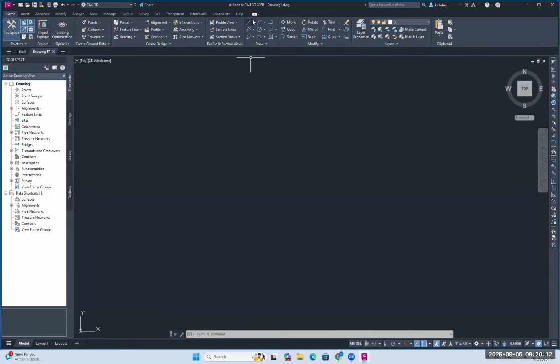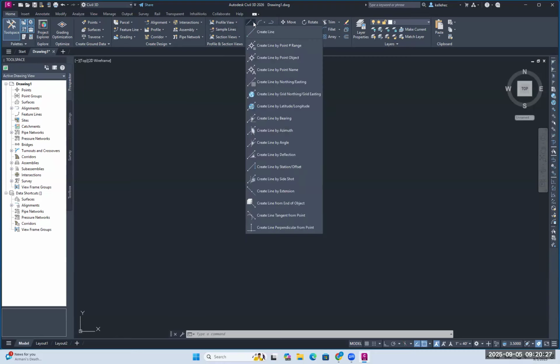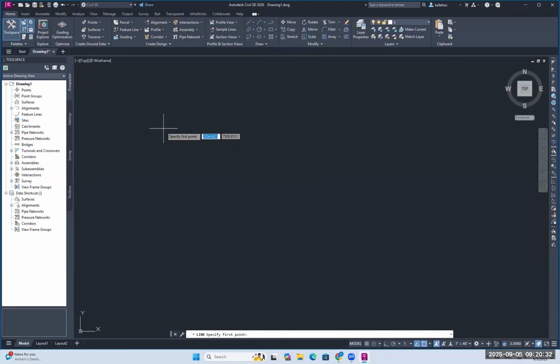I'm not going to spend too much time on it. My drawing is sort of at an angle. You can make your building, it doesn't need to be in the orientation that you see it on Google Maps. Lines, I'm going to draw my first line. I know one edge of the building is 170 feet, so all I'm going to do is click here. And you're going to notice two things. I can go all the way out to 170 feet very carefully, or I could type 170 there, and it's going to give me the edge of that building.